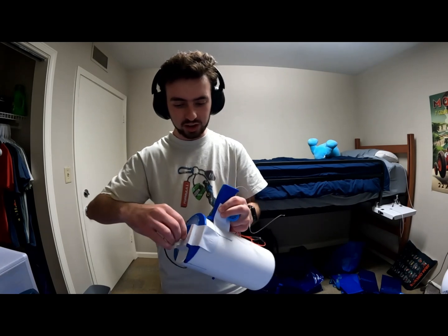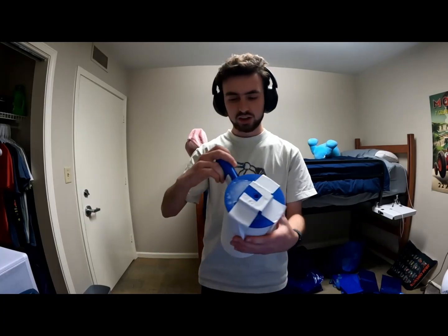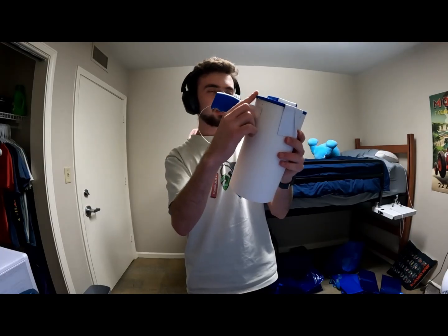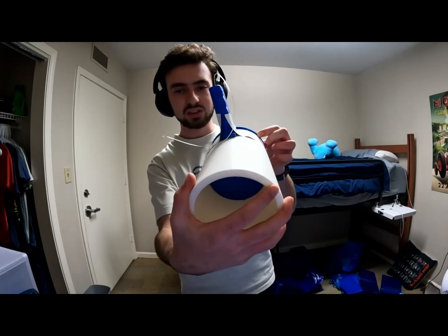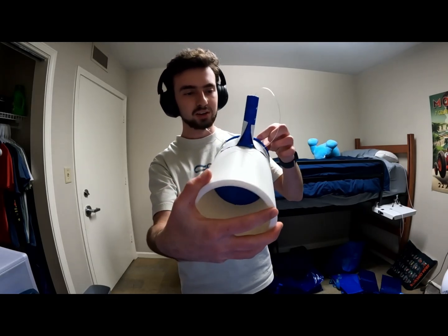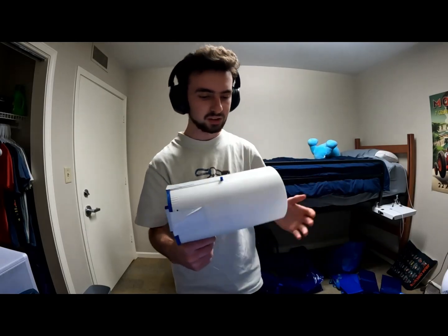However, a lot of stuff went wrong in the 3D printing. The actual barrel itself, this white piece, and the end plate weren't printed at the same size because they were on two different printers, and I guess their interpretation of a millimeter was different. So as you can see, there's this little lip right here that isn't supposed to be here. That wasn't there in CAD. Everything lined up in CAD, so all of the mounting holes that were supposed to line up didn't. You can see that's the little slot where the peg was supposed to be.